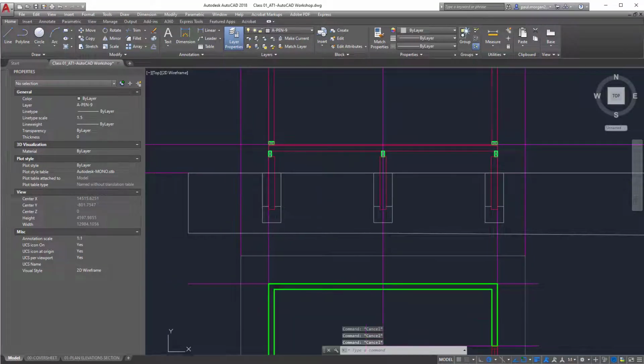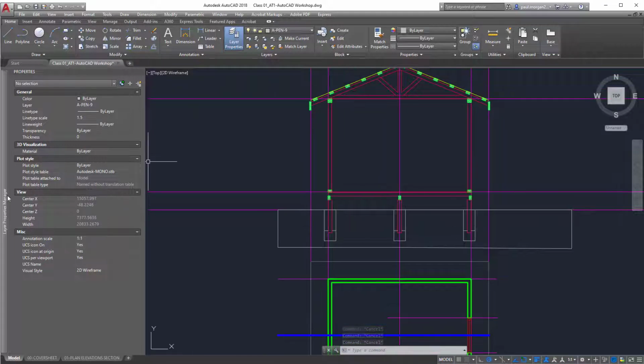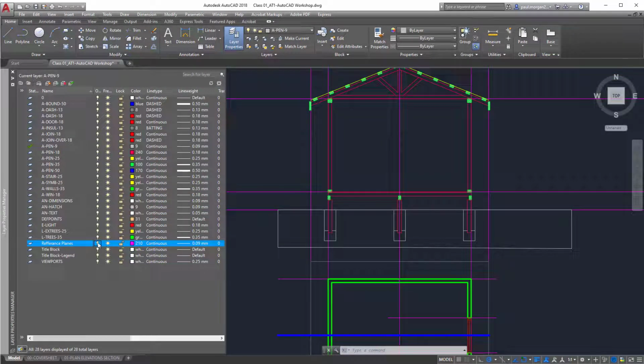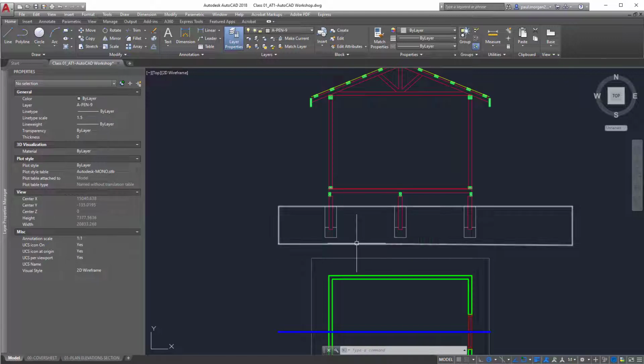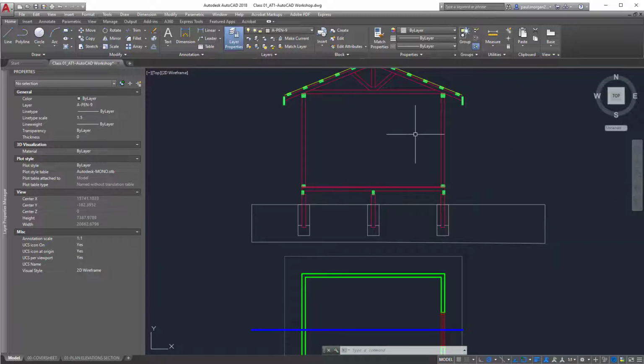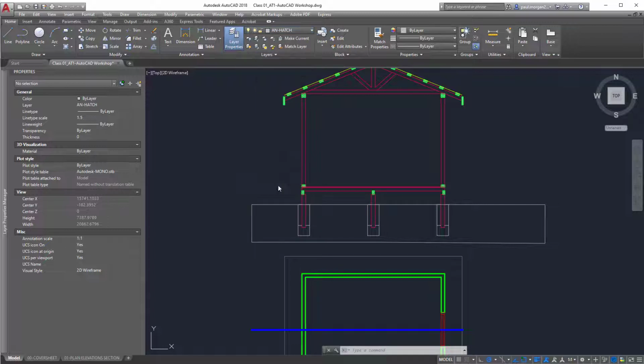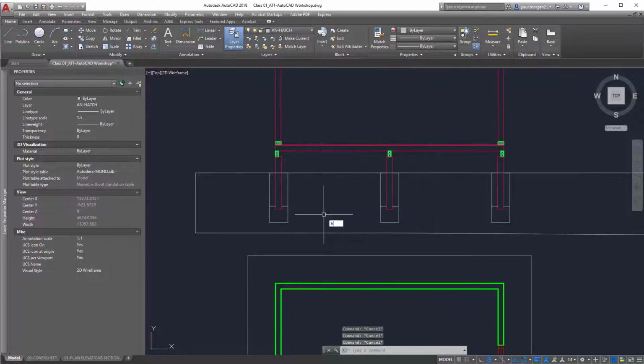All right. So now in CAD, we've got all our zones for hatches. What I'm going to do is I'm going to hide the reference planes, because every time a line intersects a zone, AutoCAD will want to hatch it as two different zones. So because we had those guidelines coming through here, you would end up with multiple zones for earth hatching when really that's not necessary. So I'm going to go to my hatch layer, which has already been created. AN stands for annotation hatch. All right, and I'll type in hatch on the keyboard.